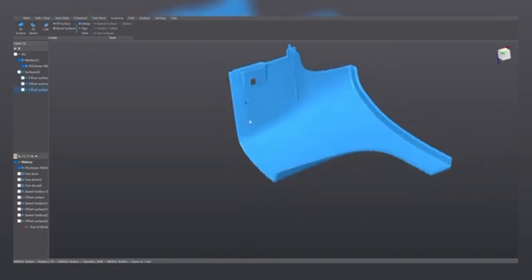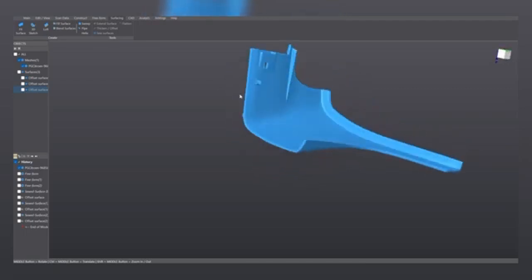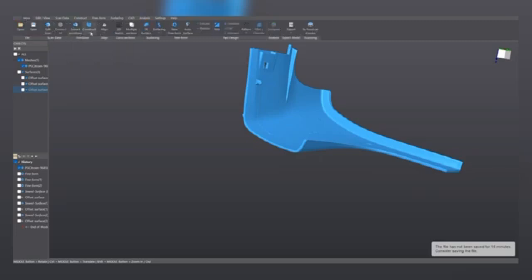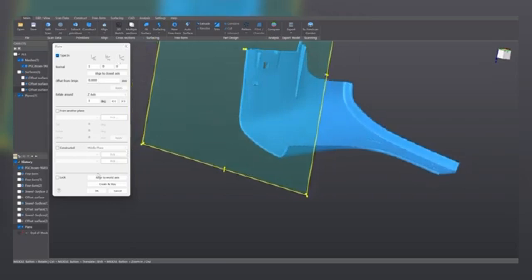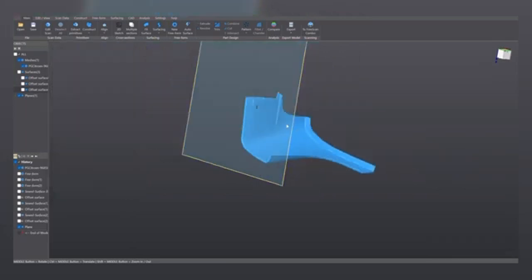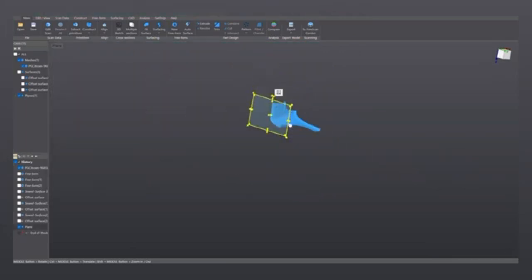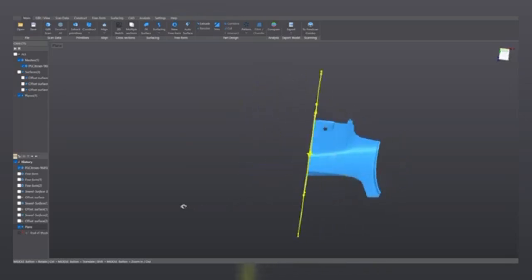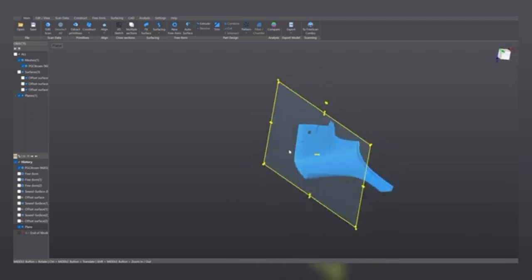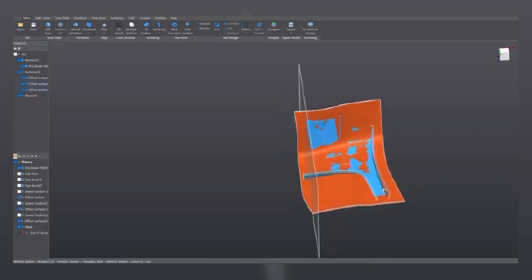Let's hide all of them first. And first thing I realize is that I need to trim them here on this side, which actually corresponds to the first plane that we used to align the mesh to the coordinate system. So instead of extracting a plane, let's simply construct it. We select the plane, this orientation at offset 0, meaning on the origin, and let's adjust its size a little bit. Right? We have our nice plane here cutting actually my surfaces. Nice.